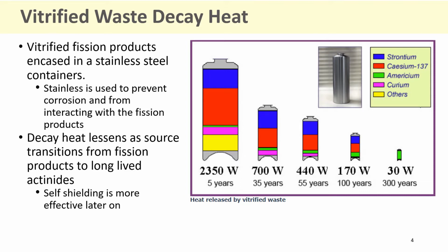The goal is to have the vitrified product remain under 100 degrees C in long-term storage. There are two types of glass most widely used in the world today: borosilicate glass and phosphate glass. Glass has become widely used for high-level waste because its amorphous and less rigid structure compared to ceramics enables the incorporation of a very large range of elements that are atomically bonded in the flexible glass structure. The density of waste glass is slightly heavier than that of industrial glasses, owing to the presence of heavy metals. The viscosity at 1100 degrees Celsius is much lower.